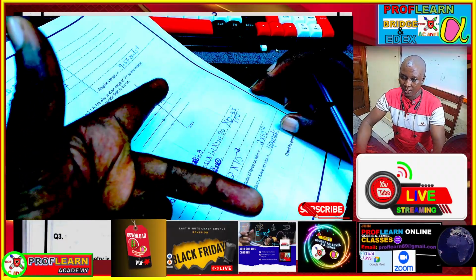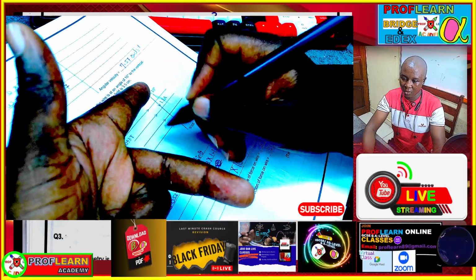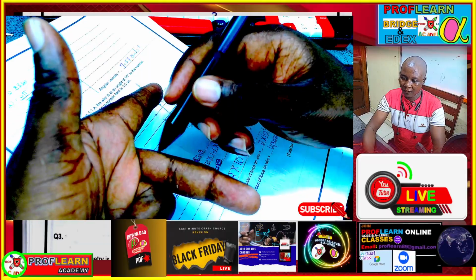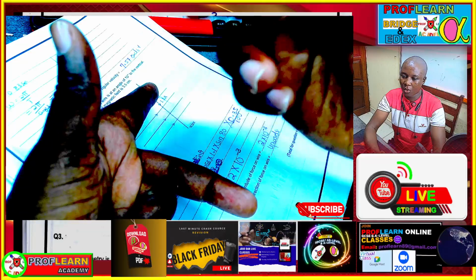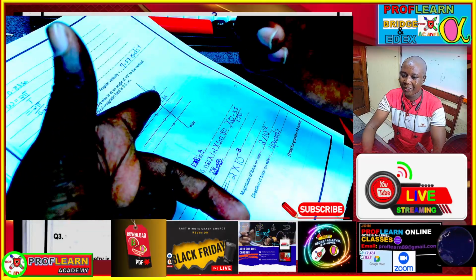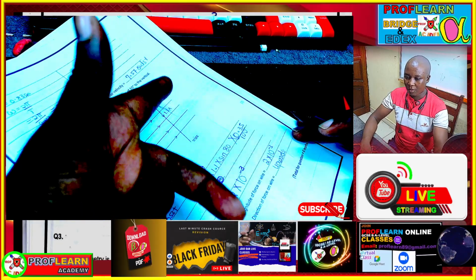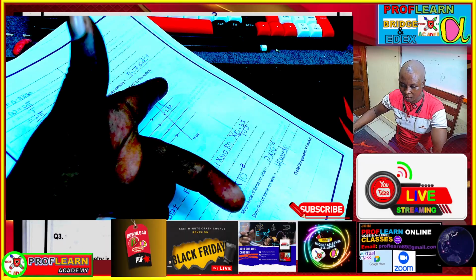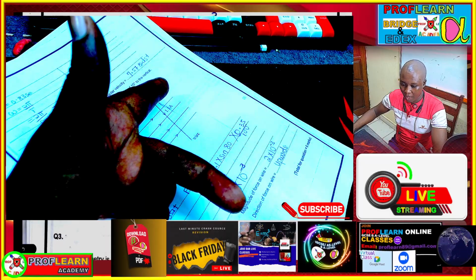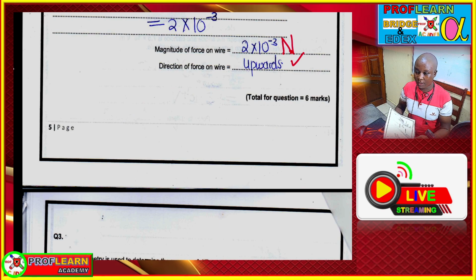The field finger is pointing in the direction where the field is going. The second finger is pointing where the current is going, like that. Then the thumb will be acting upwards. So basically that is how you are going to do that. You just use Fleming's left-hand rule. I believe you've understood exactly what you're supposed to do there. Let's move to the third question.